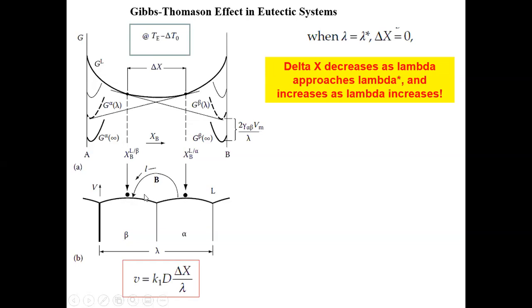So right in front of these regions, the liquid composition is far from the equilibrium XE, which is the eutectic composition at which the transformation starts, right? Because there's a lot of kinetics going on here, the liquid has a distinctly different composition than the far-field average composition. Another thing that we assume is that because we only look at a very local region, solidification and diffusion occur in this region sufficiently fast, because it deals with a very small length scale.